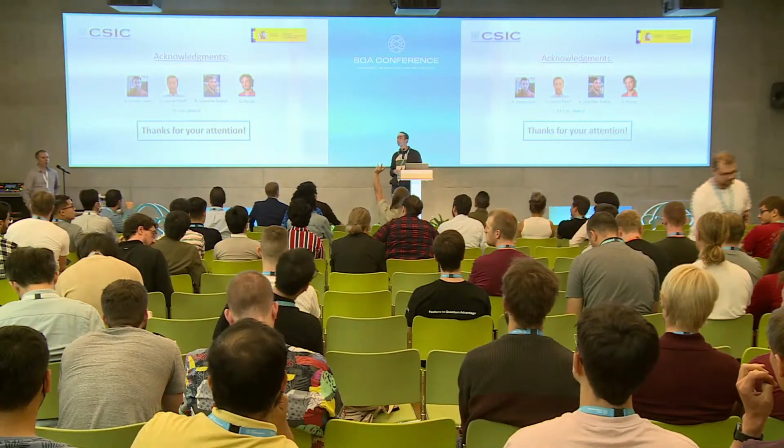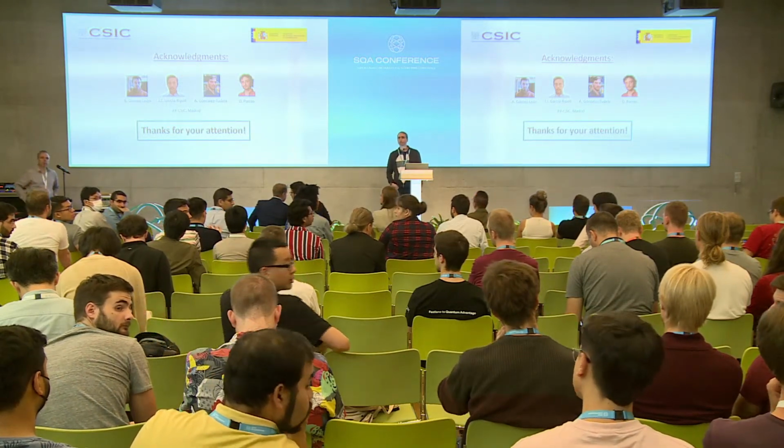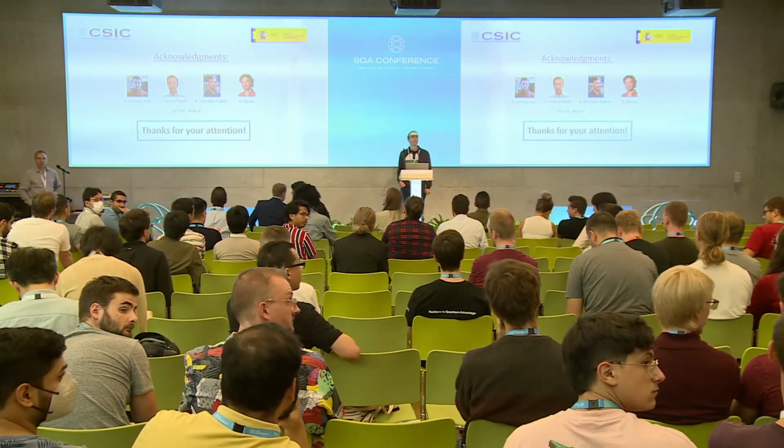Okay, there's one more. Hey, thank you for that talk. Do you need all these dissipation terms to be incoherent with each other, like separate dissipation channels? If you imagine coupling everything to a single waveguide, you're going to get some coherent interaction between sites. So do you need separate 50 ohm loads for each of your nodes?